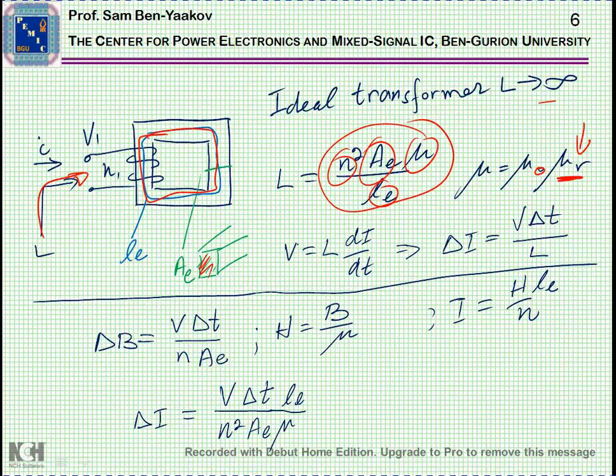If you have some inductance, then as you impose a voltage, you are going to see a change of current. And for a constant voltage, at least for a given period of time, T on, the delta I will be this value. So obviously, when the inductance is low, delta I will be large, and this is sort of a waste because there's some circulating current here that you really don't need.